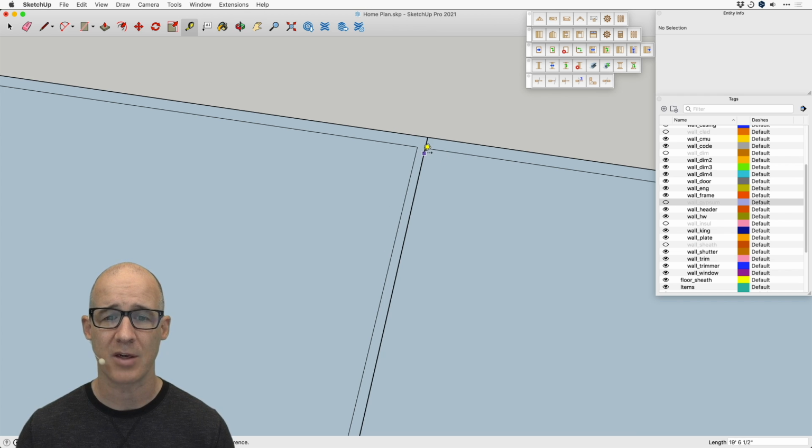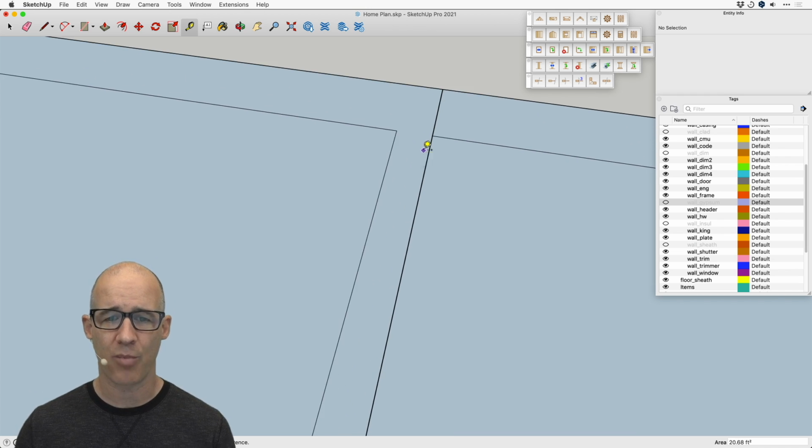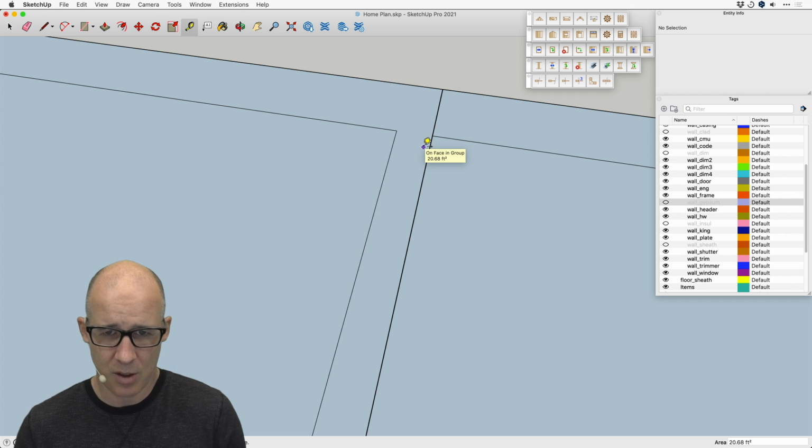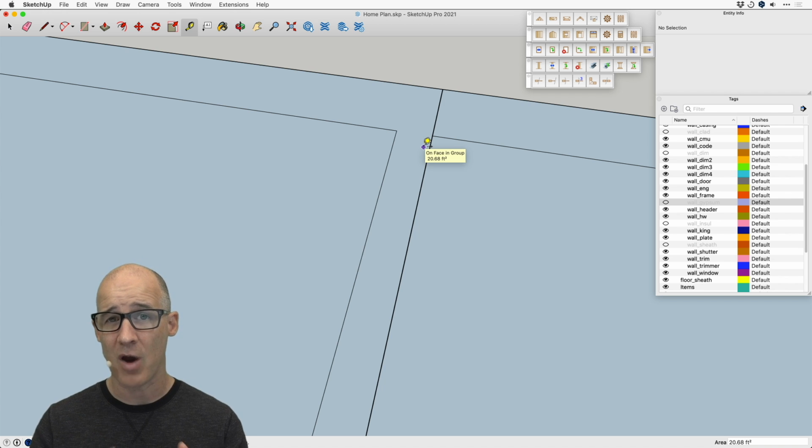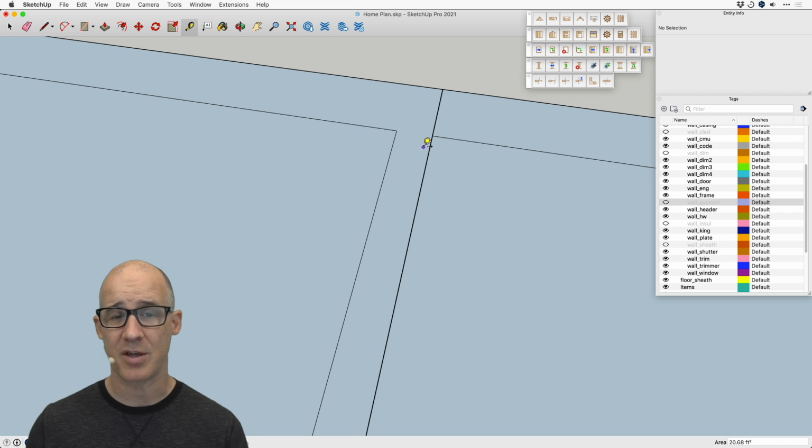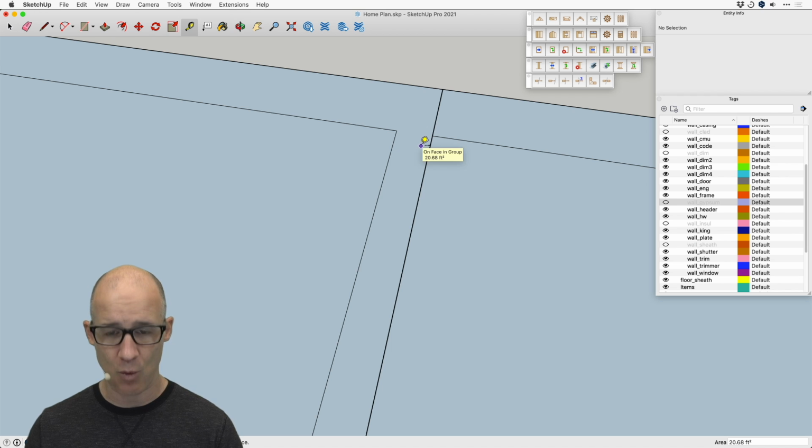We're going to learn about this. If, however, we're using the approach that I believe Nick Sonder uses, the whole point of keeping your model simple is that from an architectural standpoint, it makes it really easy to make modifications. The native SketchUp tools are absolutely wonderful for making super quick modifications. So in order to get all of this to be something where I can use the push-pull tool to pull up the walls, I pretty much need it to be all one object.